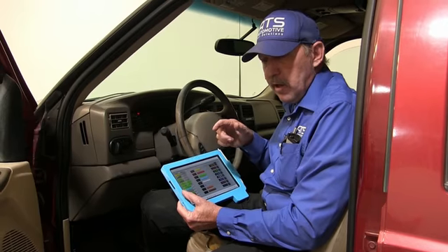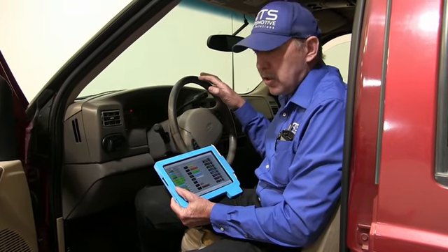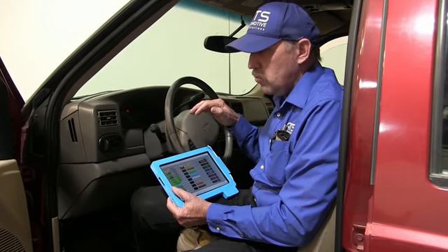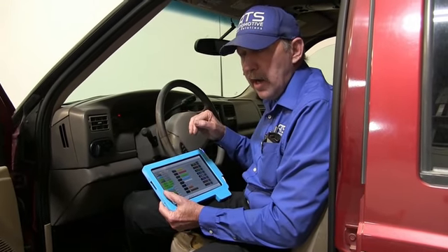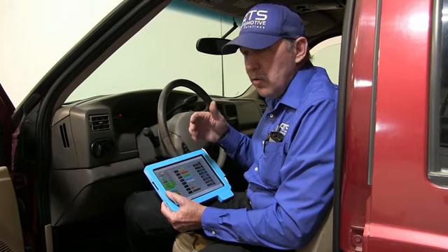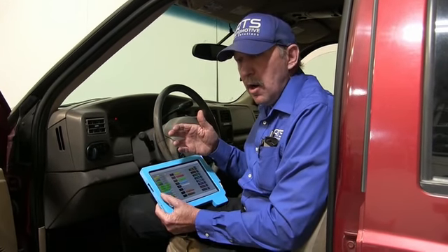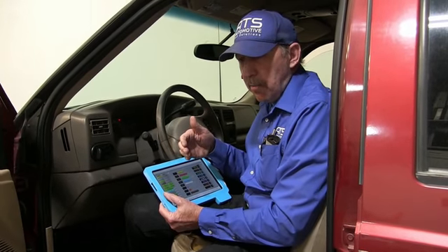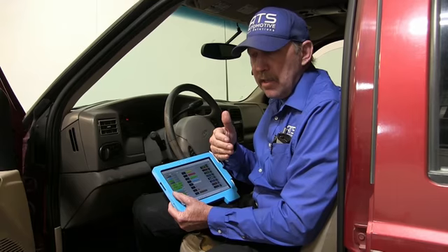Because if you're going down the road and that sensor breaks down, it'll want to cut the injectors. Well, what I've seen is on cars where you just start to move, if it cuts the injector, the car will die. Whoever programmed this, you got to think about how things are programmed, guys. When you program the car, you're not thinking that the sensor is going to break down and it's going to get the wrong count of the output speed sensor.